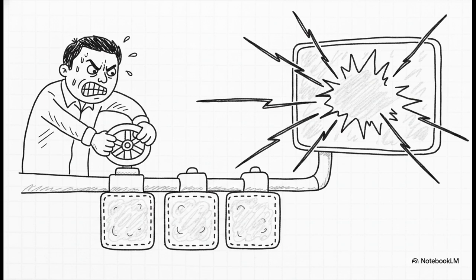And this right here perfectly illustrates the danger. Operators who don't recognize a high-order system will make an adjustment, see zero immediate movement on their trend, and just get impatient. So what do they do? They crank up the gain or aggressively open a valve, assuming the system is just stuck. But it's not stuck. That energy is just slowly making its way through multiple hidden lags. And when that delayed reaction finally hits, boom, all those aggressive adjustments hit the process at once, and it sends the loop into a violent, sometimes genuinely dangerous oscillation.